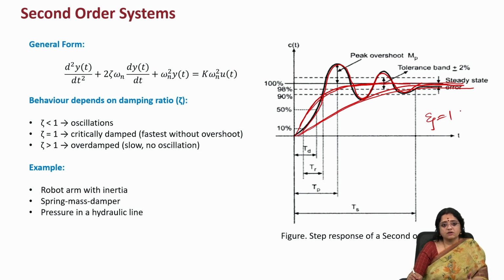Again, in the second order differential equation, we try to find the second order differential relationship between the input or manipulated variable u of t and the controlled variable y of t. Any dynamical case which involves mass and damping, inertia and valves, all these devices or cases will make the system show second order behavior.